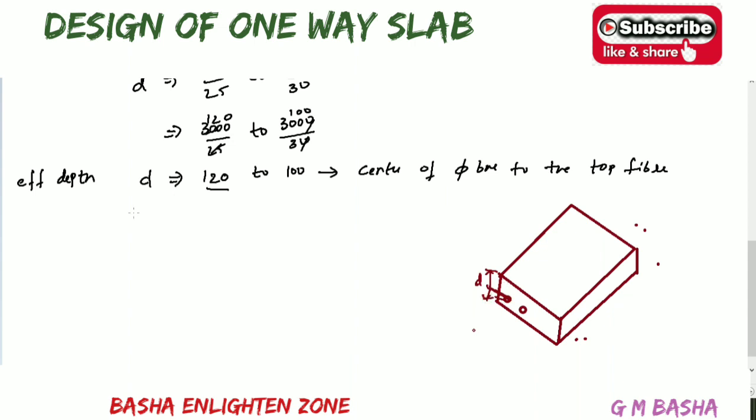Here we are adopting minimum cover: for slabs 20, for beams 25, columns 40 and footings 50. I already explained all these basic concepts in the previous lectures and uploaded them on our channel, so please refer to those and you will find it easy. The minimum cover for slab will be 20. It means from the bottom to the diabar, the cover is 20.